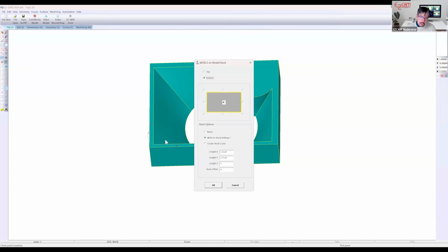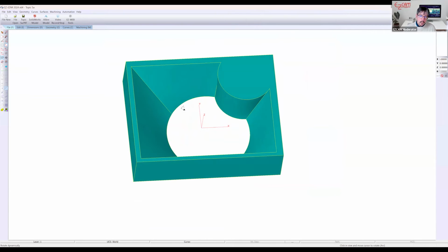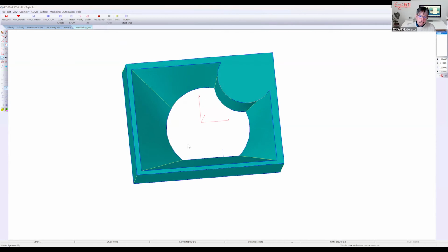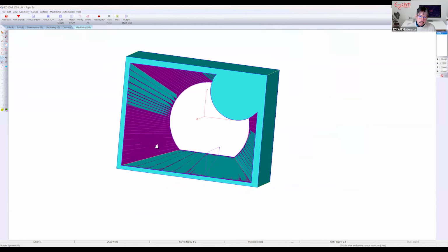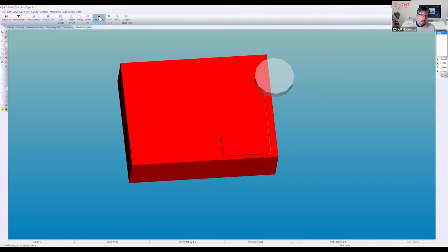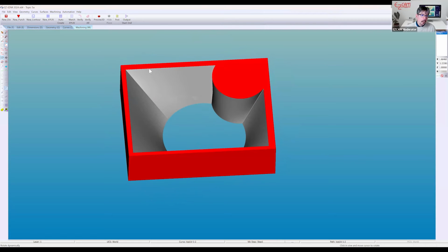I'm going to change from the top of the part to the bottom. I'll select the center of the piece. And it's taken care of for you. Now we're going to go to machining, auto create. Here it's asking me to pick the lower point on the model. So we'll pick here. Now the upper point. Starts the work step. Automatic lead in and lead out. It's created for us. And verify. And that was matched up perfectly. The 3D preview. And another gorgeous part.